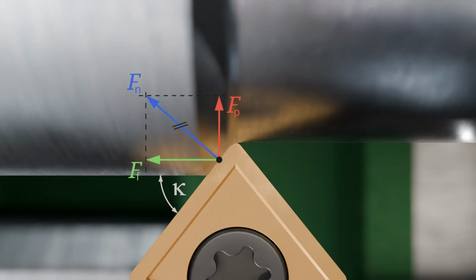However, as the force decomposition also shows, a radial force FP inevitably arises, which tries to push the workpiece radially outward. This pushing force is also called the passive force FP because it does not contribute to the machining process but basically corresponds to the force required to hold the turning tool in the radial position so that it is not pushed away itself. When turning long, thin shafts, a large passive force can cause significant bending of the workpiece, leading to poor dimensional and form accuracy. Additionally, the high passive force increases the tendency for vibrations.